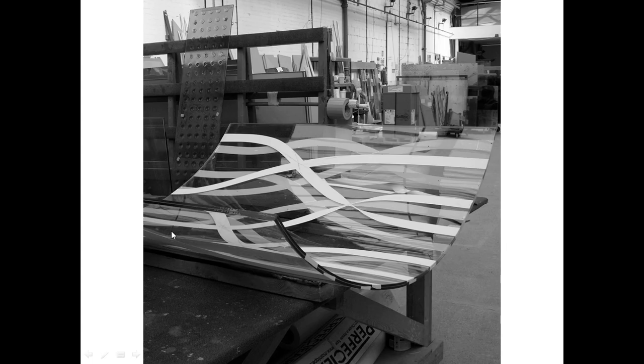As a flat piece of glass, it is placed back into the kiln on a formwork, just like with fibre reinforced plastic, for those of you that saw the lecture last week. You sit the glass on top of that, you reheat it, and it literally slumps. It falls into whatever the form of your negative is and takes that form.